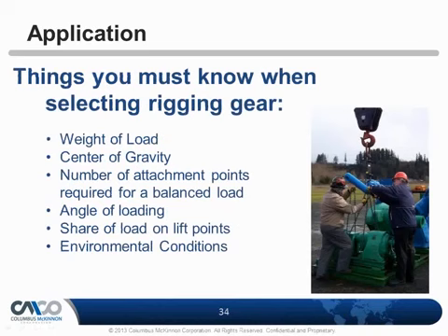So as with any rigging operation, no matter what you're choosing, whether it's shackles or swivel hoist rings, chains, synthetics, wire ropes, you need to know how much weight you're lifting, where your center of gravity is, the number of attachment points, angle of loading, the share of load on those points, and the conditions that you're working in.